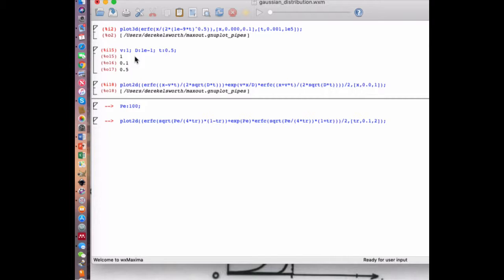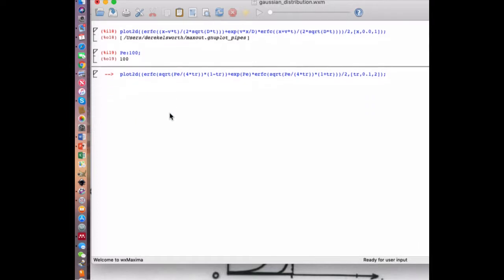So now we can define the behavior. This expression here is just the equation that was previously on the previous sheet. The one below it is now written in terms of Peclet number, Courant number, or pore volumes. You can think of this as a number being 0 when it's 0 pore volumes, no water's gone into the sample. 1 pore volume is where the front has completely swept the sample down to the downstream end. So this is the Courant number, or pore volumes. And this involves time, and this involves the effects of dispersion.